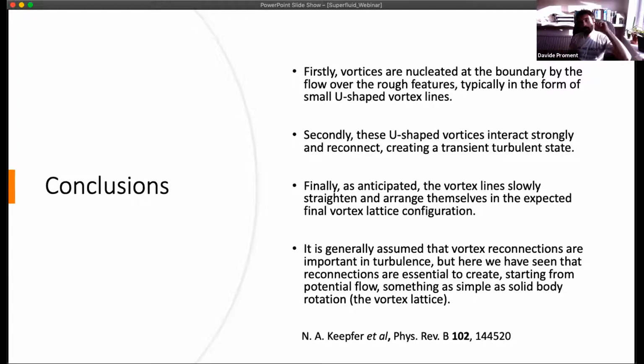So when you go through the transition, let's say by moving the transition from the top of the cylinder down to the bottom. I just wonder if you're aware of those results, and whether you compared some of those simulations done with the Biot-Savart model with some of yours, for example, for the line density or something like that.